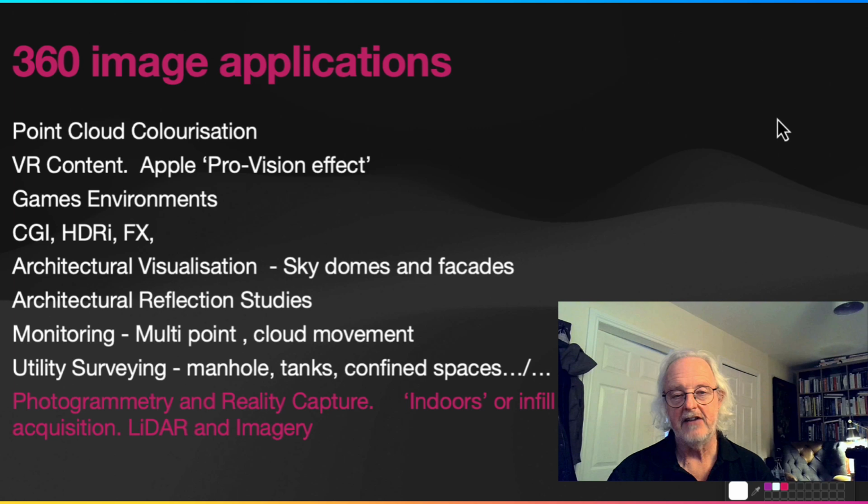A 360 image allows you to verify your CAD in the office, okay, to infill the stuff. And 360 imagery is a bit of a bridesmaid in the geomatics land survey industry, but it is going to be hugely important because this is a revenue stream that can be added very simply to your existing services, whether you're doing topographic surveying, utility surveys, point cloud, all sorts of issues. Adding 360 imagery or quality 360 imagery to your deliverables can be hugely beneficial.